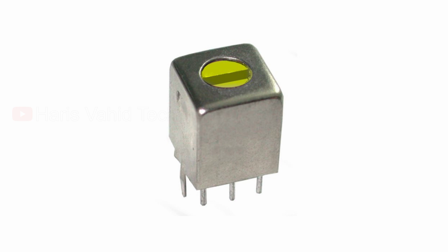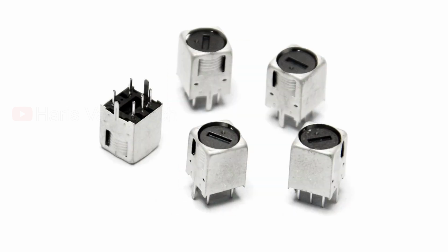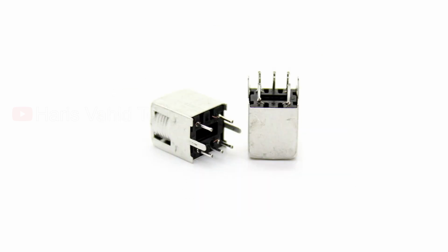For example, in satellite dishes, the microwave downlink signal received by the dish is converted to a much lower IF at the dish to allow a relatively inexpensive coaxial cable to carry the signal to the receiver inside the building. Bringing the signal in at the original microwave frequency would require an expensive waveguide. The second reason, in receivers that can be tuned to different frequencies, is to convert the various different frequencies of the stations to a common frequency for processing. It is difficult to build multi-stage amplifiers, filters and detectors that can have all stages track in tuning different frequencies. But it is comparatively easy to build a tunable oscillator.